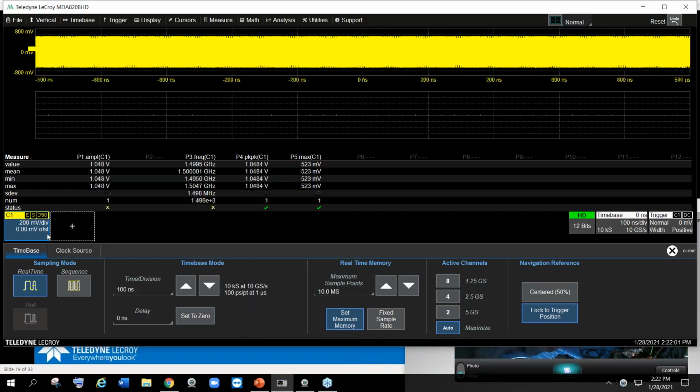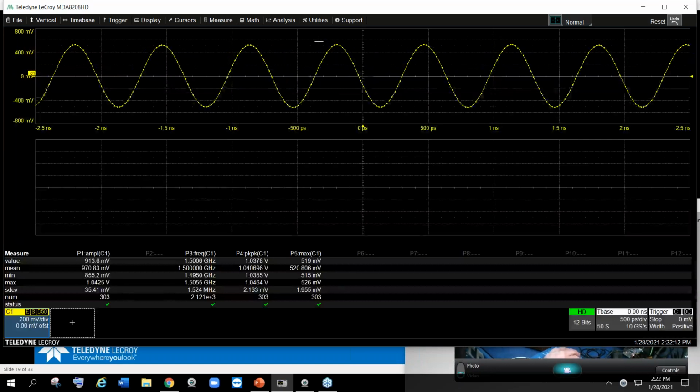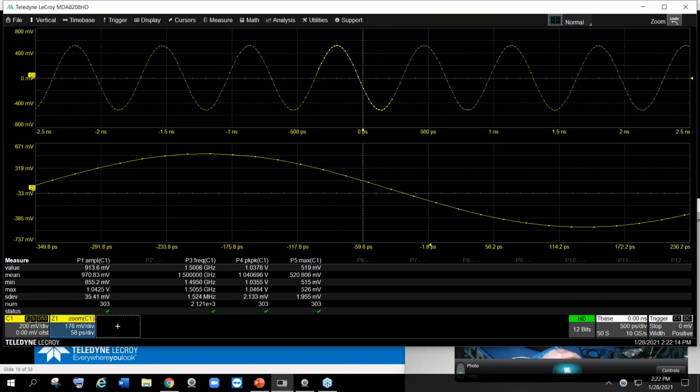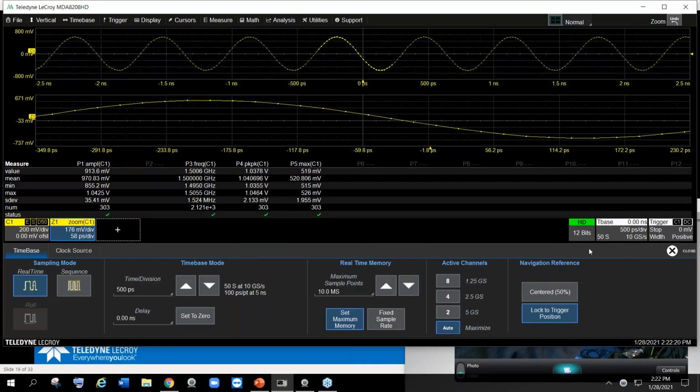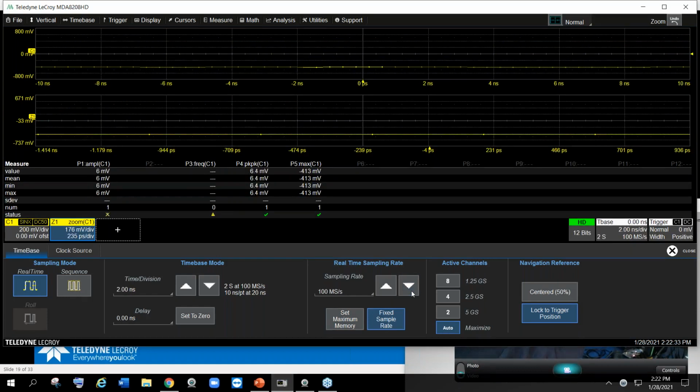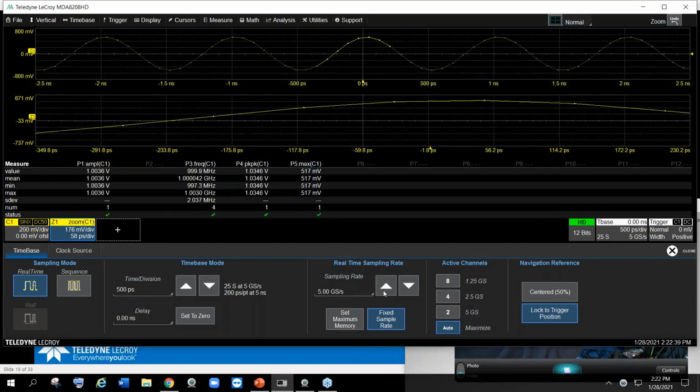Let's look at that waveform. And we're at 50 samples. Let's stop it. Let's go single. You can see, I closed this. It's comprised of digital data points, right? As we reduce the sample rate, let's go normal again. As we do reduce the memory or reduce the sample rate, here we're at 50. Well, I'll just go with sample rate right now. Oh, wow. You can see we are only capturing only a little.